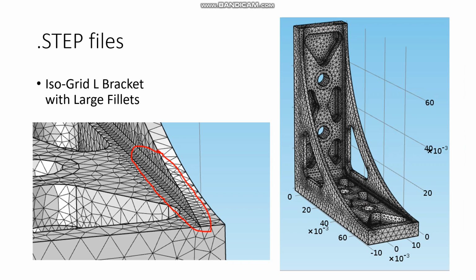Originally, I had issues meshing this, but putting a small radius in the area circled helped meshing go smoother in COMSOL.